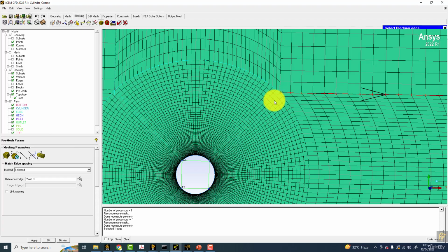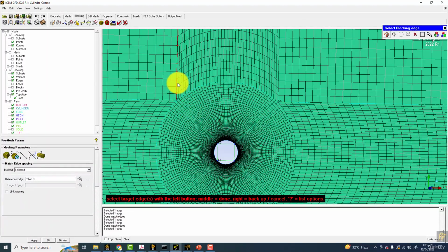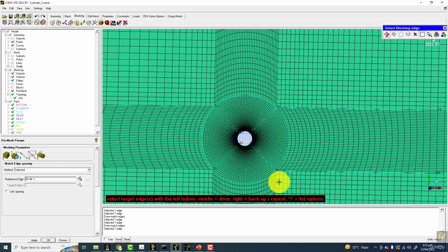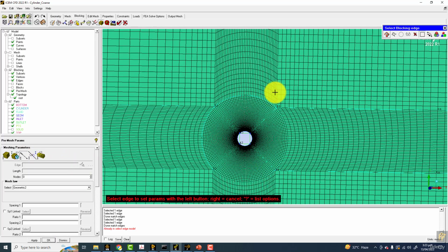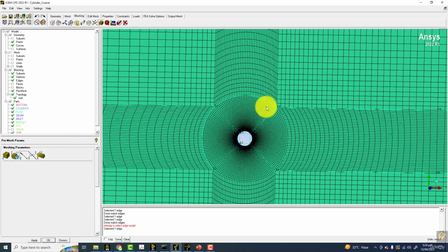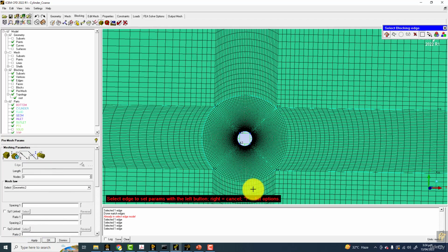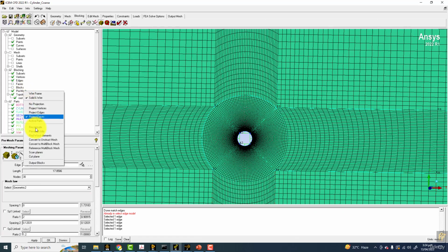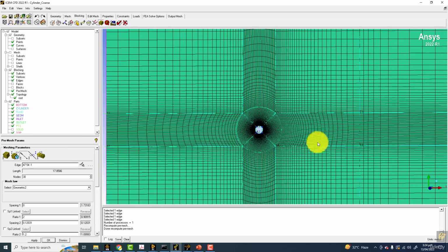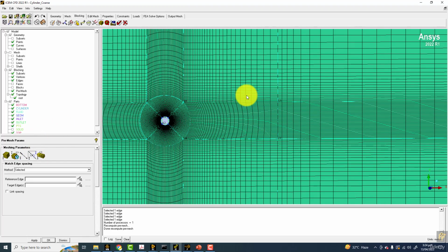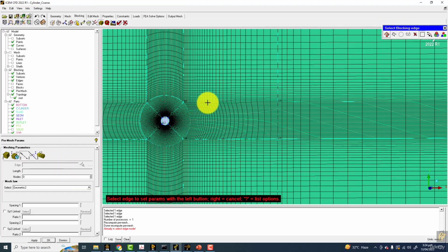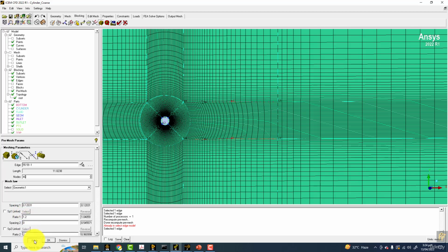So I will be copying meshing parameters from the inside to the outside of the blocks, the neighboring blocks. And this should give us a more decent mesh. And similarly over, not here but here, and also here, and right click on the pre-mesh and recompute. So this is a more refined mesh, and I can put more cells here, like maybe I can put 40 cells.